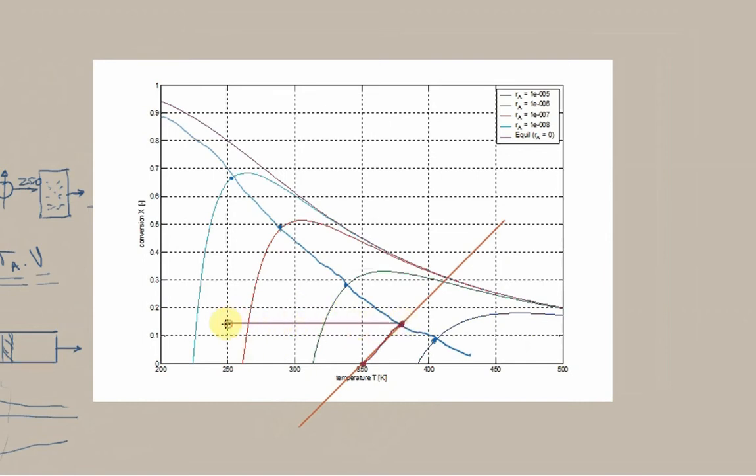And by the way, I'm just using 250 because I know I want to do a bit of stepping up here, but in reality, we would never use such a low temperature because we typically do want to operate the reactor. We don't want to refrigerate things. It's expensive to cool things down on a plant because then you need an additional refrigeration system and so on. So normally we shoot for returning to 300. You can get away with 300 Kelvin using a cooling tower or something like that. But anyway, for the sake of this illustration, we'll cool to 250.